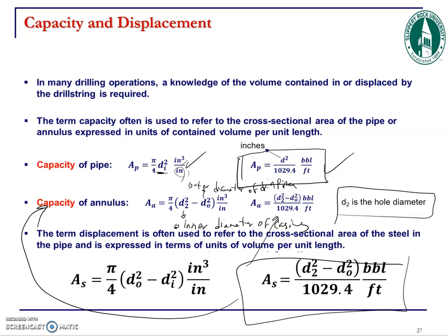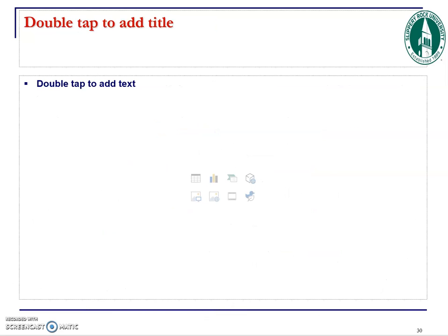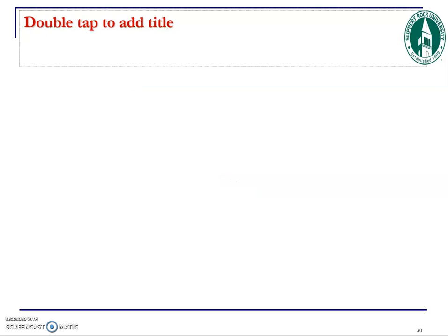So assume that you have all the drill strings inside your wellbore, and you want to do a trip. Remember, a trip is, for example, when you want to change your bit, so you have to take all the drill strings out of the wellbore, correct? So what happens when you take out all the drill strings? Think about it. You have a wellbore full of liquid, right?